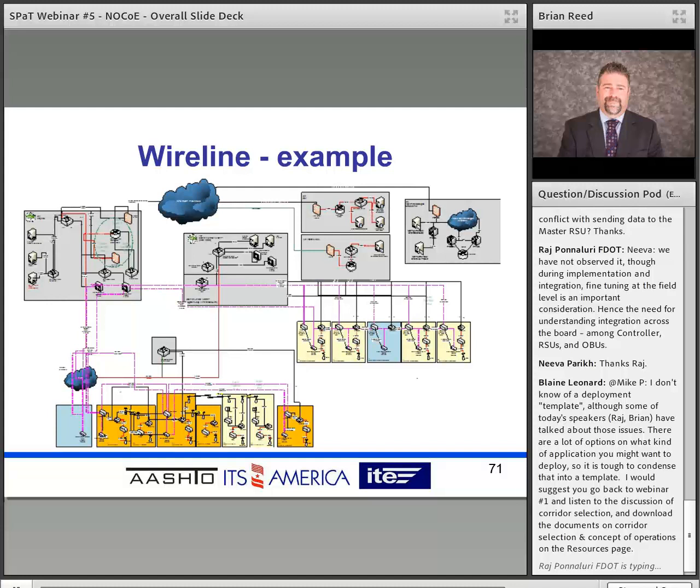data aggregation is done through the city network out to a head end with a new firewall and router implementation and an ISP connection. That way, from a bandwidth standpoint, there's no impact on, we'll call it, the enterprise network for the city. As we roll from 30 RSUs deployed within this configuration out to 80 RSUs, that bandwidth allocation or usage becomes a critical driver to how this gets implemented at scale. The SCMS provider is a connection via the internet itself.